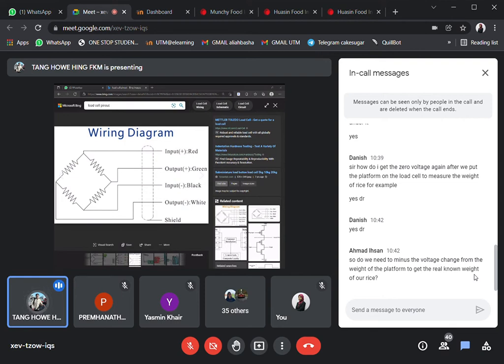So if it is already in step number 3, and you measure that there is a difference between your sensor's mass reading and the gold standard mass, that is the error. After you get several measurements, let's say 5 or 10 repeated measurements, the maximum error will reflect the accuracy of your system.